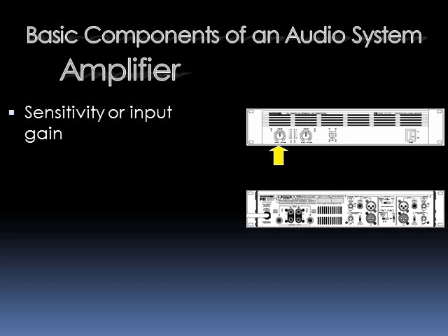Yes, it will react like a volume up, but if you turn the knob all the way to the right, you're saying don't attenuate any of the signal coming in. Just run it full out. As you turn it down, it attenuates that signal, cutting it back, and therefore not driving the amplifier wide open or hard. It's always a good idea to roll them back a little bit as a sensitivity or safety factor.